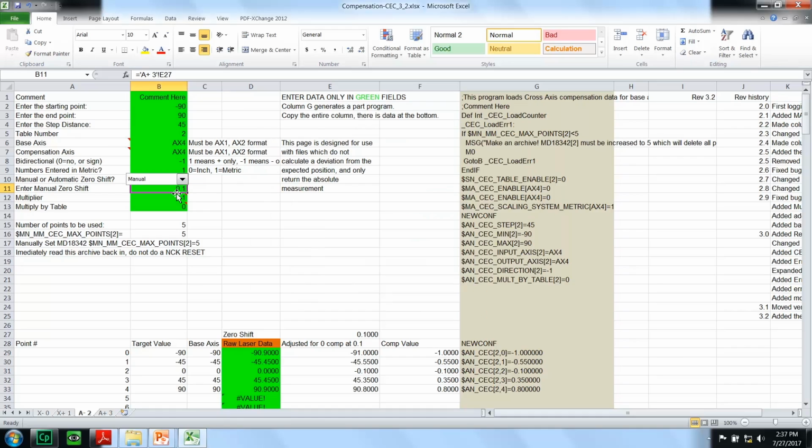When we set up a rotary laser, we usually drive to the negative end of travel, or negative soft limit, somewhere near there. We zero the laser out there. We move all the way through the range of motion. We typically pick up a value at axis 0. If we don't shift and correct that properly, we've moved the position that we used with the test bar.